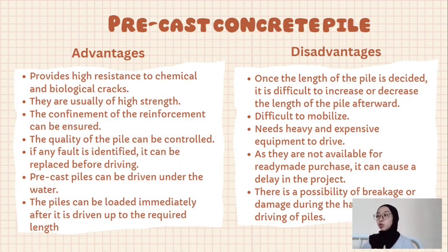The precast concrete pile is cast in the pile bed in a horizontal form if they are rectangular. Usually, circular piles are cast in a vertical form. Precast piles are usually reinforced with steel to prevent breakage during their mobilization from the casting bed to the location of the foundation. After the piles are cast, curing is performed as per specification. Generally, the curing period for precast piles is 21 to 28 days.